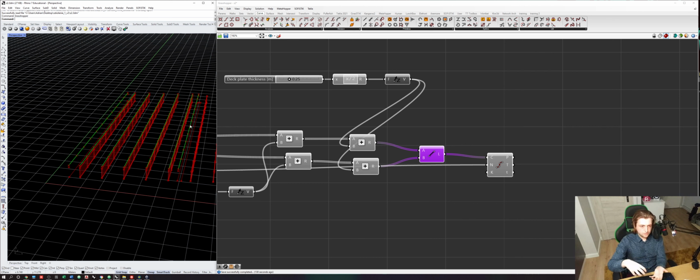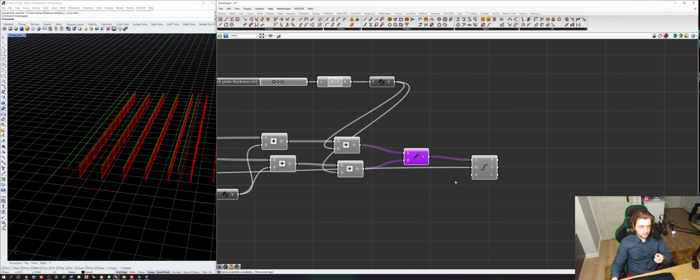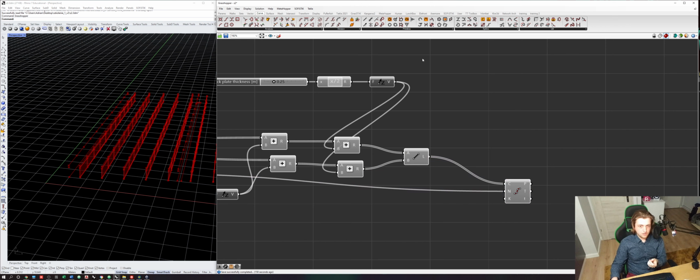Having these 4 sets of points, we will be able to create a 4-point panel. Okay, so let's do it in practice, and I think it will then be better understandable. So first we have to eliminate the first and the last line and keep those two sets, and then divide them and repeat this process in the second direction.